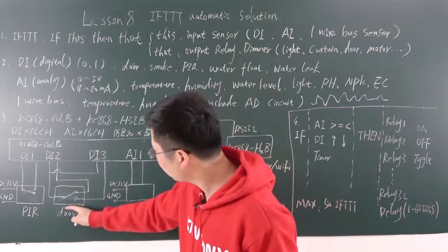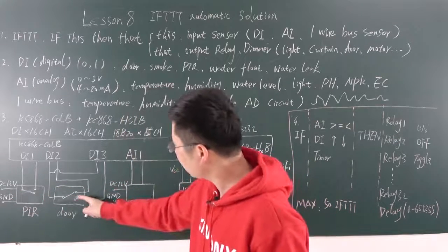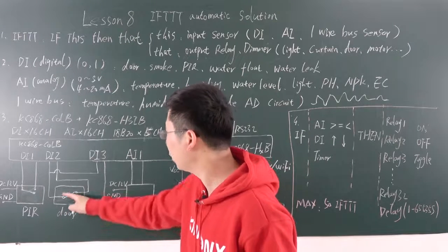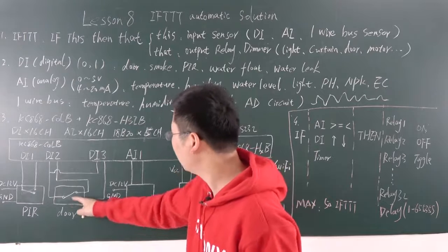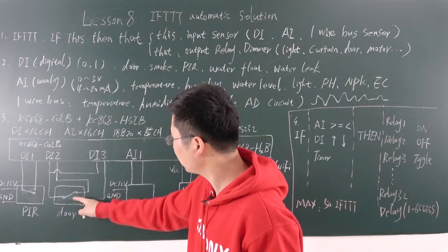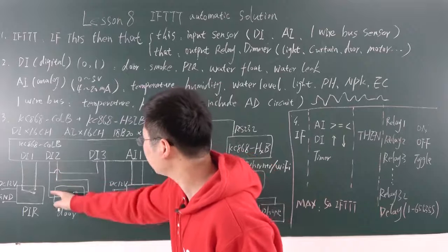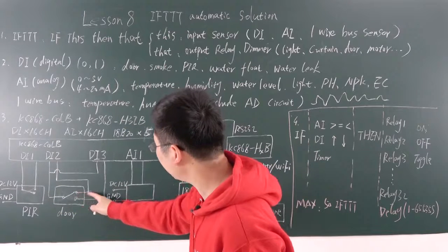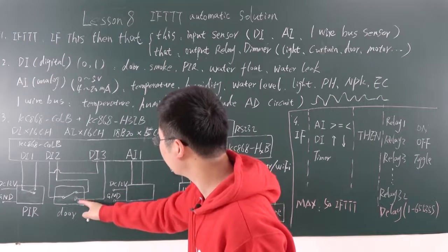This door sensor, you can see, does not work with a power supply. It just has a contact output like a relay, but does not need power. When the door opens, it has a normal close and a normal open, 2 points. And this is common for the ground. And this is for 2 outputs, normal open and normal close. This is normal close, normal open.